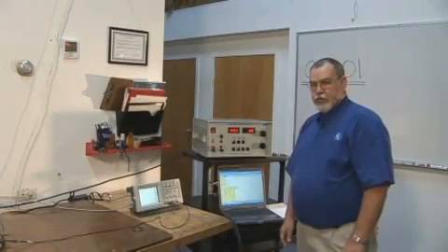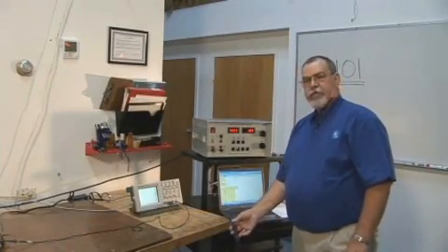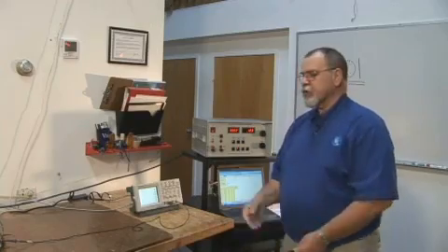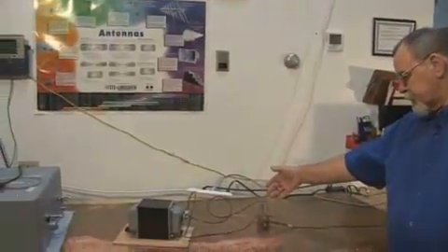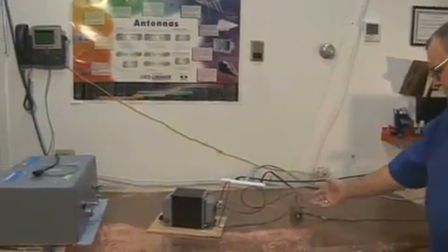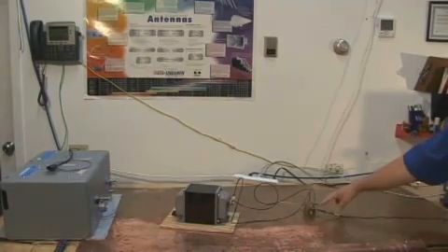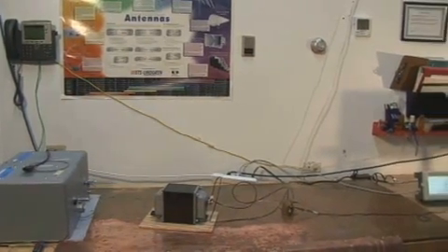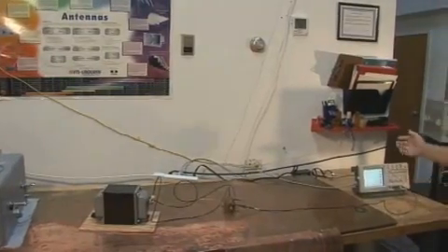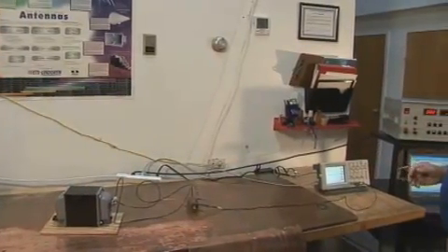Well, we're in the laboratory doing our CS101 pretest calibration. As you can see, I have connected the secondary of the transformer to the half-ohm resistor as prescribed in the standard. The oscilloscope is our measurement source. A measurement instrument is connected to the resistor to measure the voltage across it.